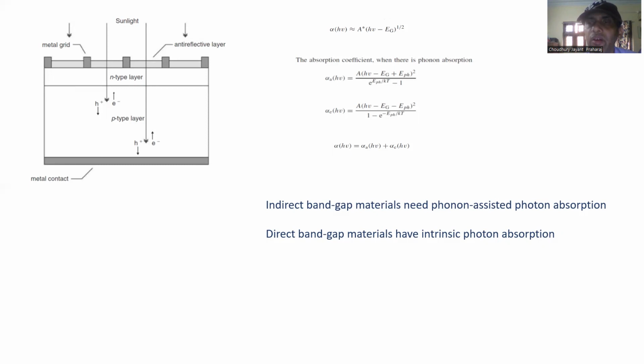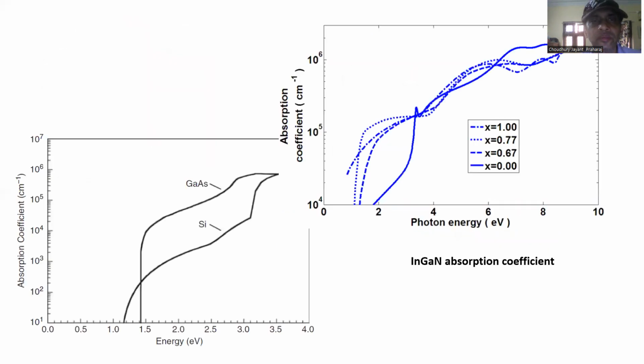For example, at high levels of alloying, the electron states can change not only quantitatively, but also qualitatively. And similarly, the valence band states can also change qualitatively and not just quantitatively. And when there is a qualitative change in the nature of the conduction band states and valence band states, the nature of absorption can change. So all that needs to be kept in mind as fundamental physics considerations that must be used to optimize device design for these solar cells.